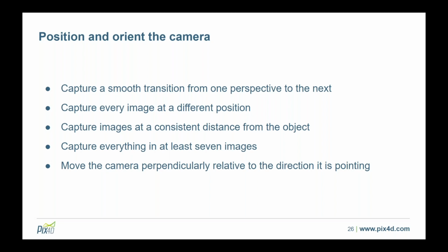However, as a starting point, I believe that capturing everything in at least seven images is a reasonable starting point. That's in part based on my own experience and also thanks to the experience of other team members at Pix4D. Some of you may have already gotten the job done with less image content, and if that's true, then I'm happy for you and keep it up, right? However, if you are just getting started or you find that your results are inconsistent or inaccurate, one of the best ways to tackle the problem is to simply capture more images.